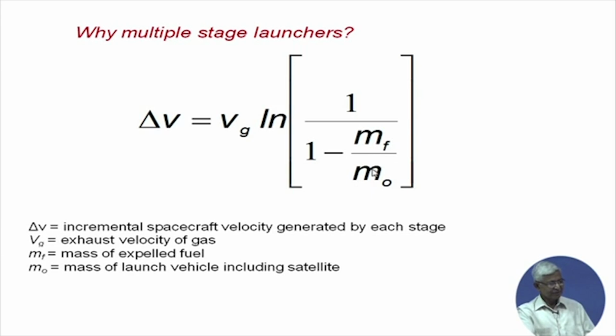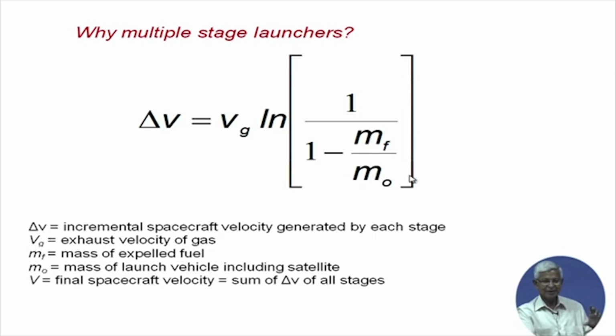So, how do we make these two near to 1? After some fuel is exhausted, I remove some part of the dead weight. That is the trick. That is how it is a summation of many dead weights, a summation of many segments of the rocket. So, when one segment of the rocket fuel is exhausted, that portion of the container also is exited out. Therefore, the remaining ratio is again quite high, near to 1.